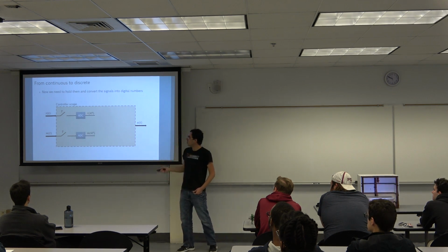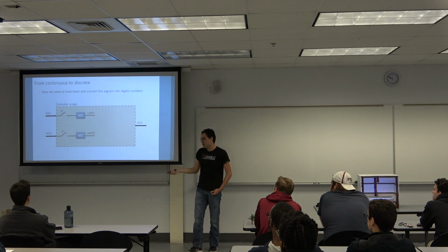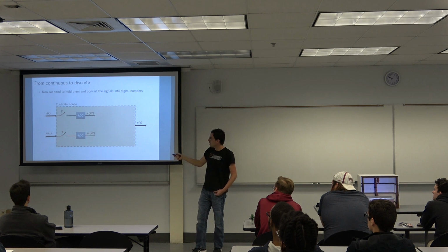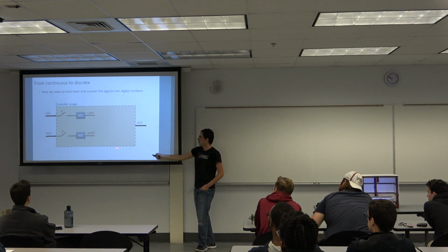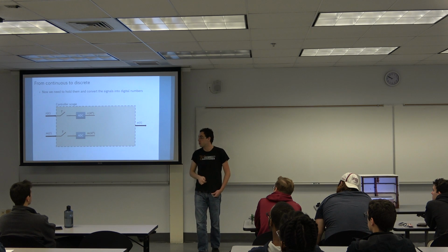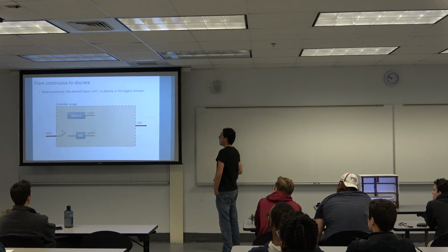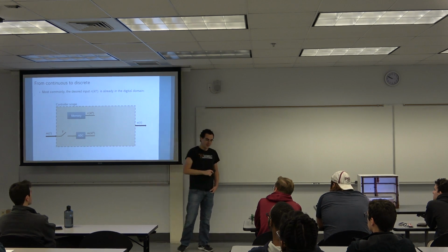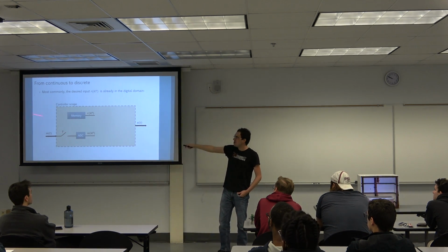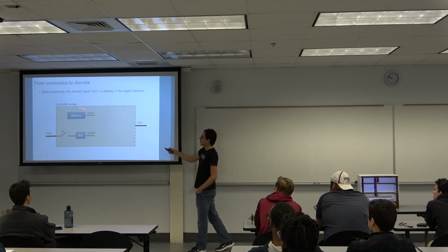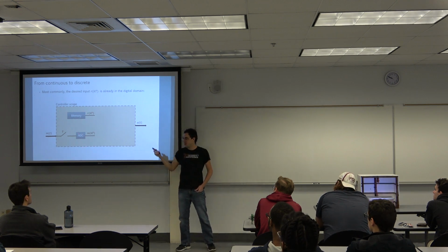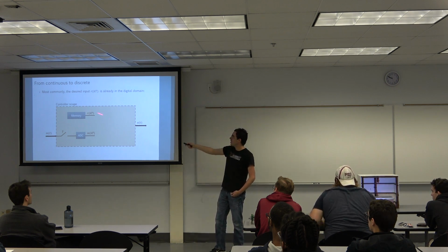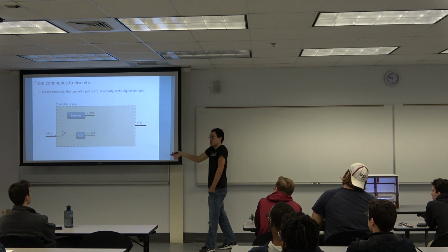And of course, this is something about the digital controllers. We need something to convert this analog signal into a digital number. So for that we use an analog to digital converter, ADC. And I must say that in most practical applications, it doesn't make too much sense to have r of t getting in, because we usually have the desired control state in the memory of the digital controller. So I'm replacing r of t with a number that comes from the memory.